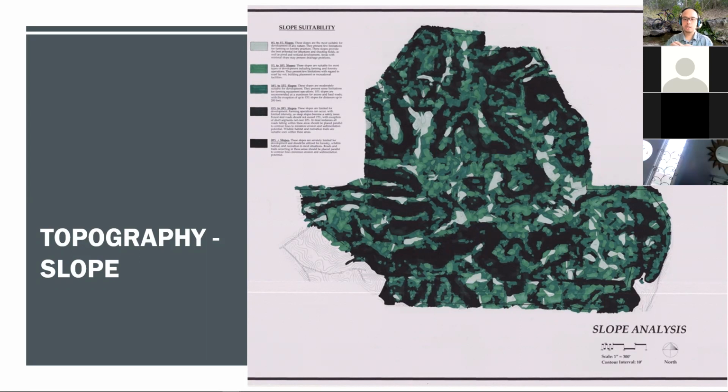In contrast, in locations with freezing winter temperatures, you would generally avoid development on steeper slopes, because vehicle and pedestrian circulation systems on steep gradients can create safety hazards from icy and sloping surfaces. You get a nice big ice slide.